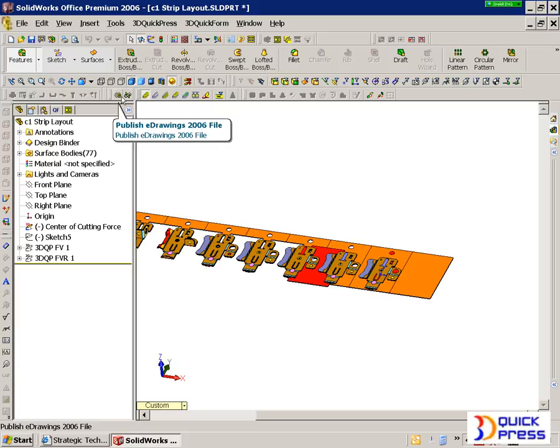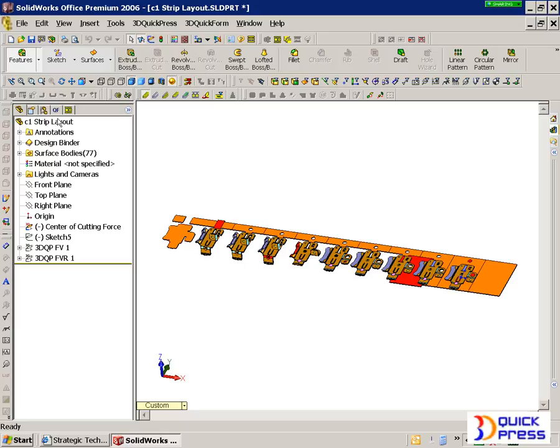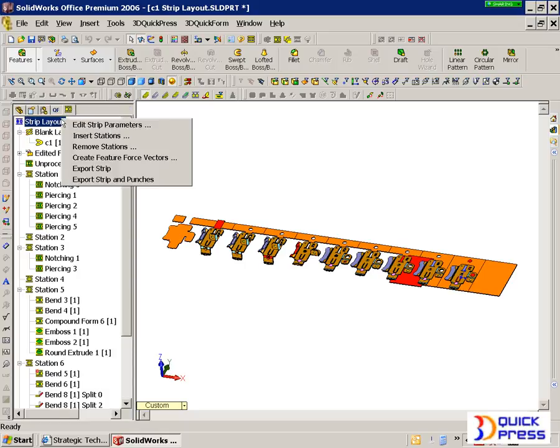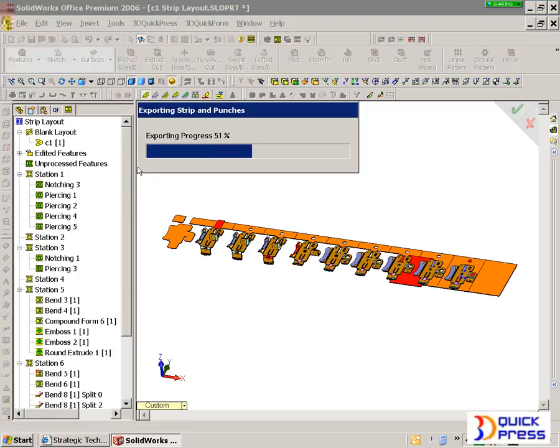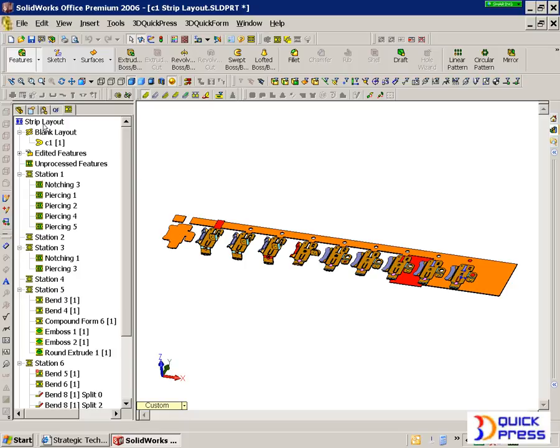We have a technology in SolidWorks called eDrawings. It's kind of like PDF for engineering, except it's easier. What it will do for you is it will automatically create the actual data in 2D, 3D, it doesn't matter, and it will automatically package the viewer with it if you choose. So the user that's getting it does not have to worry about downloading anything. Even with Adobe PDF, you have to download it, and you have to know how to do all that, and a lot of us don't have the time to do it. So let's go through here and show you what an eDrawing is. With one click of the button, I can quickly get this into a format that I can send to a client via email.